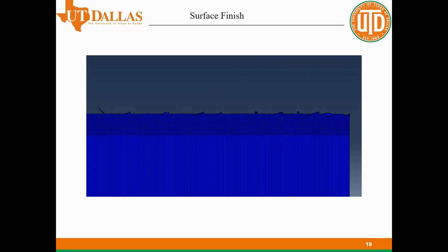We said that one of our objectives was to compare the surface finish left by the tool, and in our preliminary simulations, we were getting some incredibly rough surface finishes at the beginning of the process, but smoother cuts by the end. It looks like the blade isn't cutting low enough in some spots, but we're keeping the top of that blade at a fixed height, so we were wondering why some of these elements were remaining uncut.